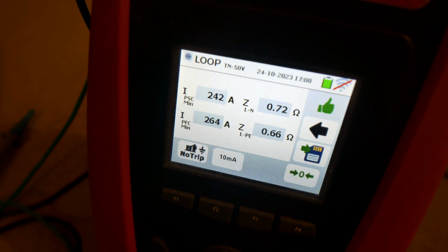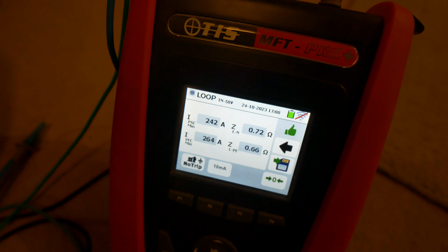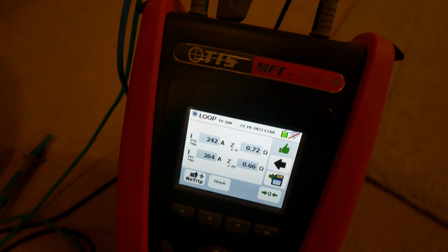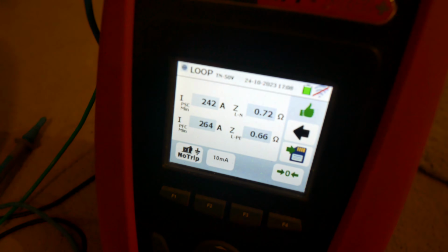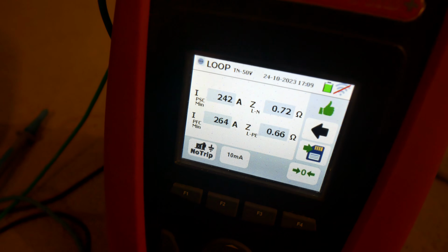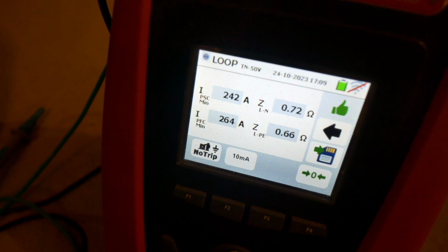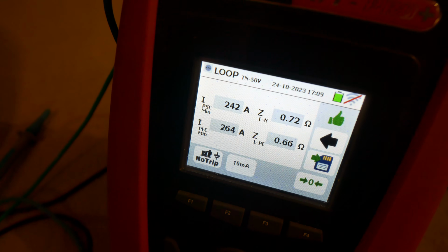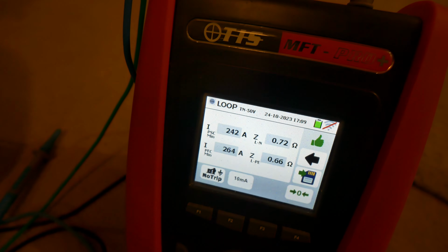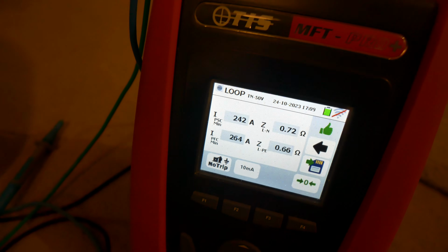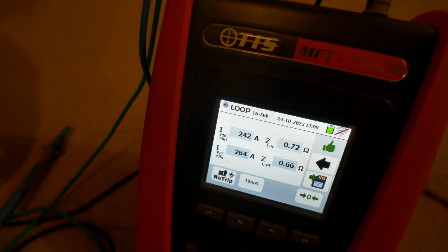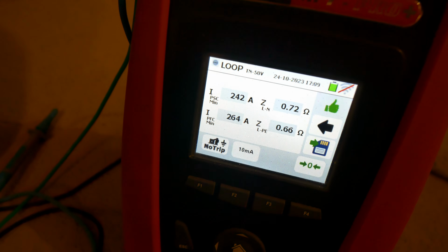There's no RCD testing to do on this. The lighting circuit, should you wish, you can go and take a Zs measurement at the end of the circuit. It's perfectly acceptable, as lots of people have made the point before in terms of Guidance Note 3 and the Wiring Regs, that if you want, you can use the calculated method of using your Zdb and your R1+R2 to determine what your Zs is. Obviously, if you're opening that fan up, there's live terminals at play. It's not as easy to get that measurement as it is just using a socket adapter into a socket front.